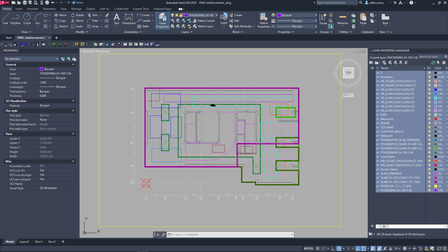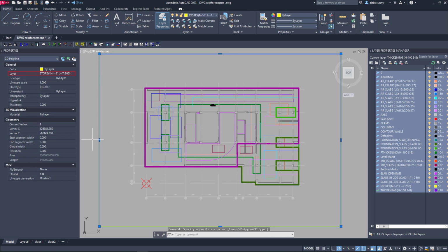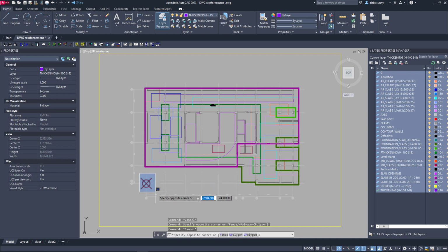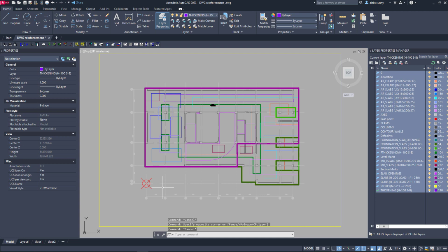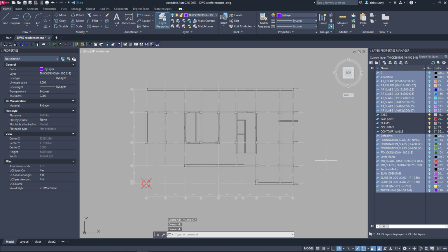This drawing contains a frame that indicates story and elevation on which it is necessary to import objects, and a base point that corresponds to 000 coordinates in LIRA-CAD system. Also, in this drawing, there are axes and main load-bearing elements, columns, contour walls and beams.